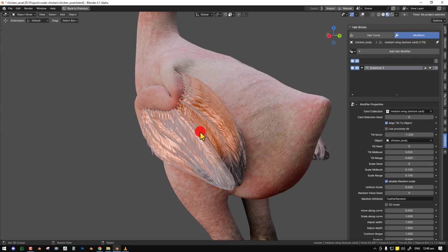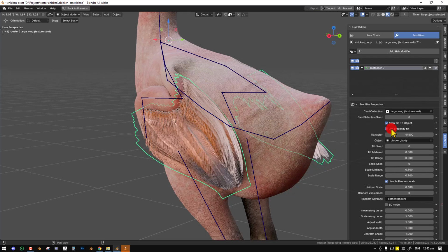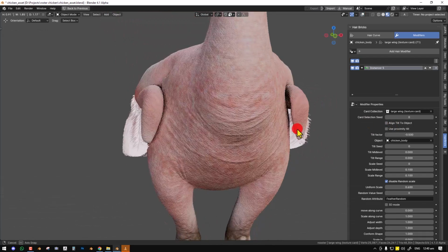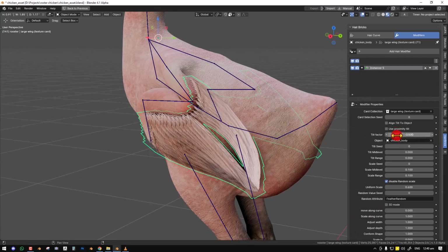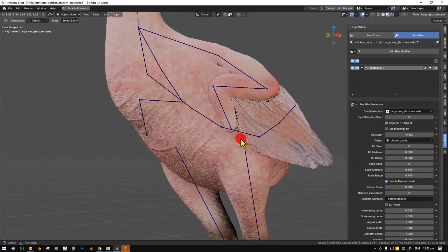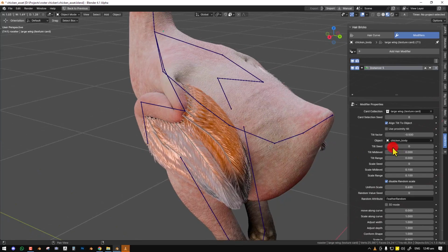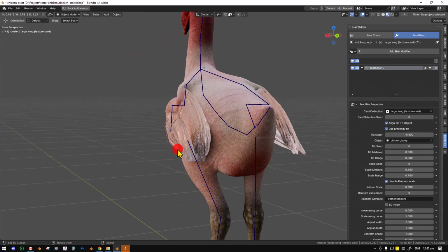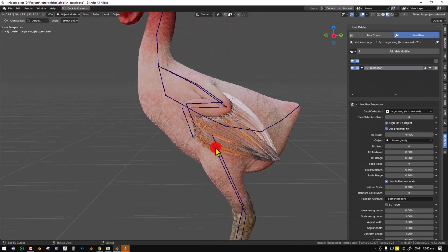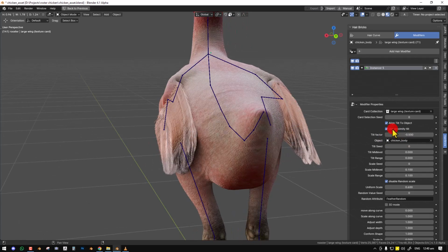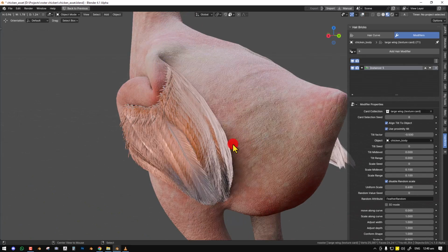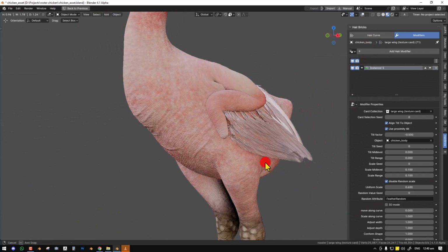So if we make sure we have the right ones selected, you can get different results. So this is what we get without the texture being aligned. If you enable the tilt, it faces the mesh now, and you can use proximity tilt, where it tilts to the mesh based on how close it is to the surface. So this works well if you just experiment and see what works best for your particular assets.